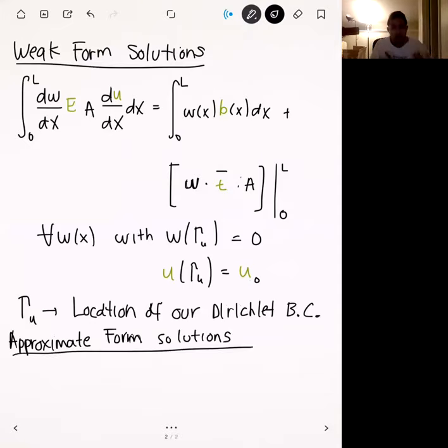And so this methodology that we're using, where first we assume a form of the function and then we plug it all in, is the exact same way that element stiffness matrices are derived for the finite element form. Normally what we do is we make two assumptions here. Let's take the elasticity case.